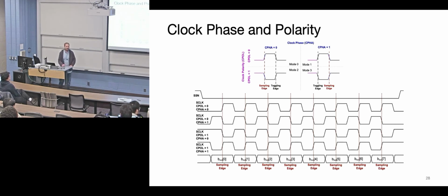I had a project one time where my microcontroller could not do one of these. This was like early 2000s, where my microcontroller just could not do all the polarities, and my device needed it, and I spent a whole day banging away, trying to figure out what the problem was. I eventually just had to switch the, I think it was an accelerometer that I was using, to a different one. But now it's pretty standard to have lots of different versions.